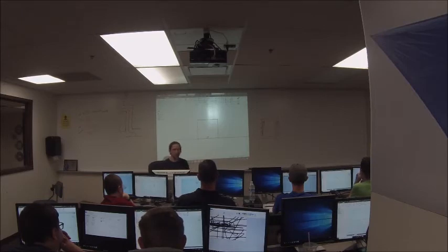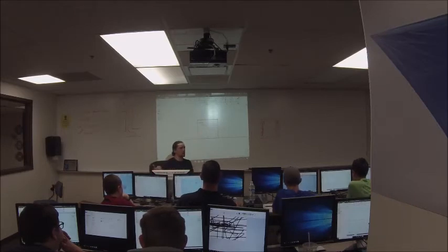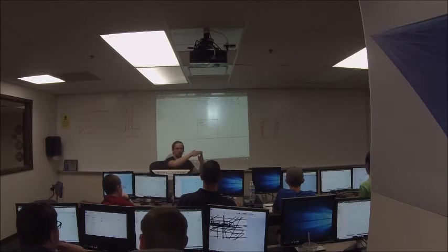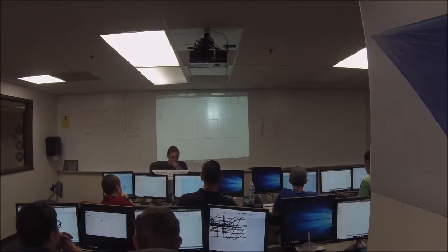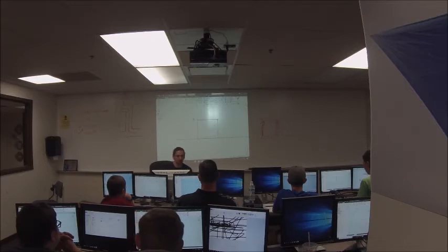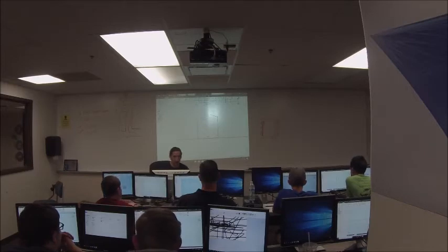There's always two icons. If I hover over this corner, you can see there's two icons, but those two icons are the same constraint, because it's one corner, two lines on one corner. So you can just do the same thing, hover over the line, and you can see which line they each belong to. They both show up. You can hover over the one you want to delete, left click, right click, just like we did before, and click delete. And because I deleted that horizontal constraint before, now I can move this line around and it's not attached to this corner anymore.